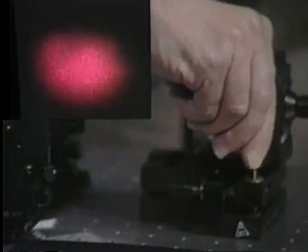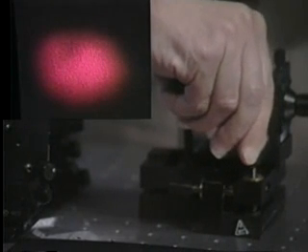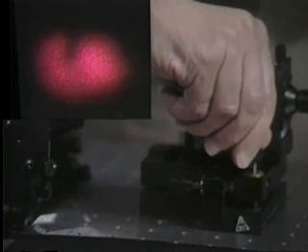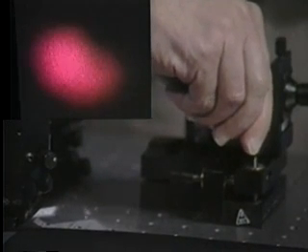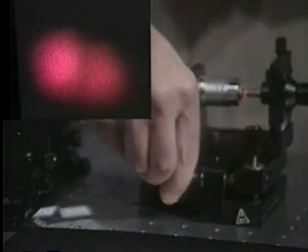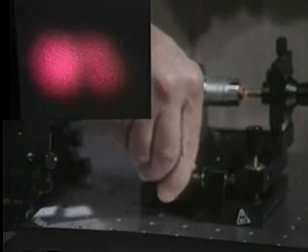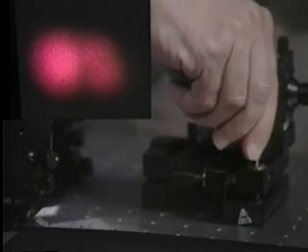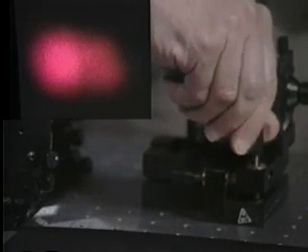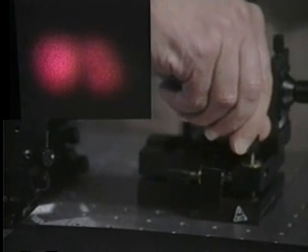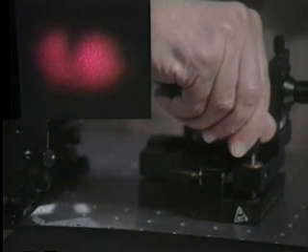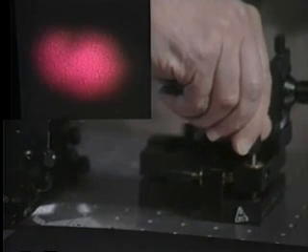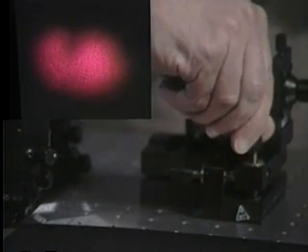And this is the so-called multimode. What you're seeing are different transverse modes that can propagate in this fiber because the core diameter is bigger. But I'm going to leave it to you to explain exactly why you get higher transverse modes propagated in this fiber. Again, the wavelength is the same. The only difference is that the core diameter is bigger.